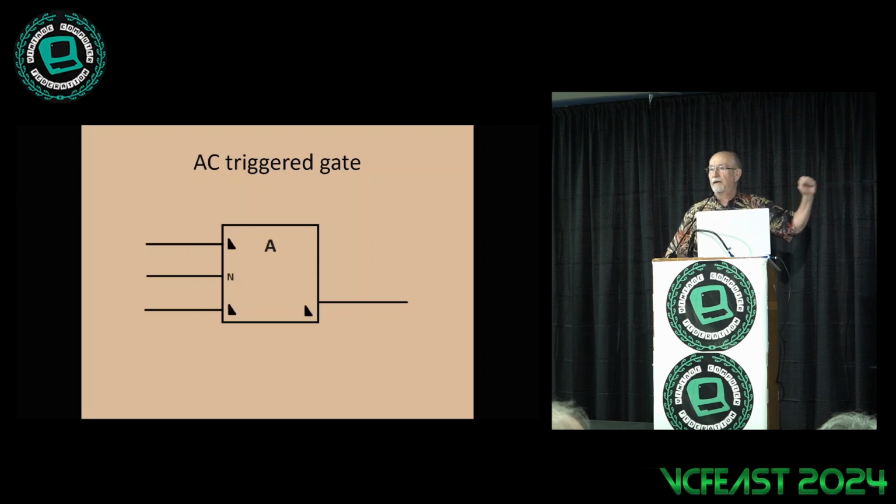So you see a letter there, and it means this gate will produce a pulse on the output if it sees this falling edge, but only if the other inputs are active. Think of them as arming. So the other ones arm the gate to be sensitive to the edge, and then if it sees the edge, it emits the pulse.